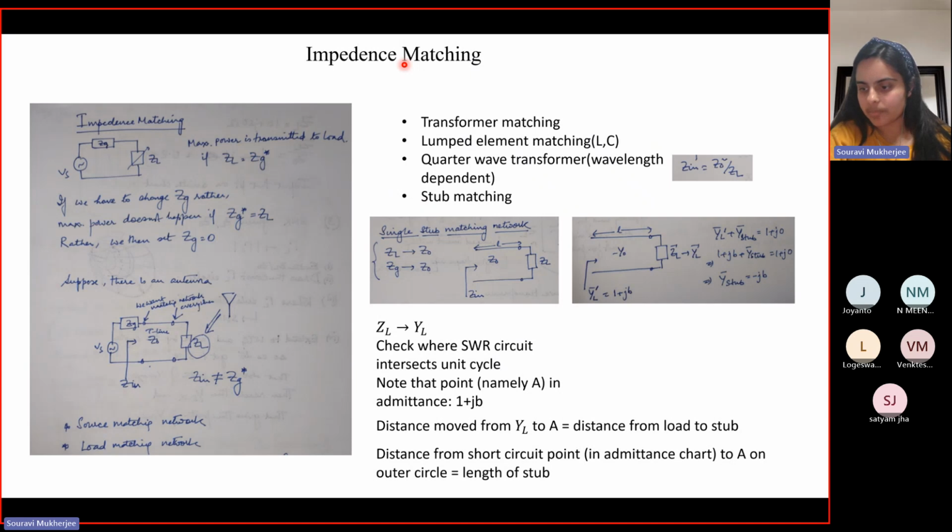Now talking about impedance matching. So we know that when there is impedance matching, what happens? There is no reflection, right? So that means if you have some source impedance or some impedance at the generator end, and if there is some load, maximum power transfer. So if you try to write it in terms of both resistive and reactive loads and try to find out, you would see that the maximum power is transmitted when ZL is the complex conjugate of your generator impedance, right?